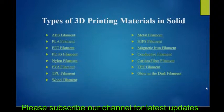Okay, talking about the materials, I hope ABS and PLA are known to everyone, and we also have PET. ABS stands for acrylonitrile butadiene styrene, PLA stands for polylactic acid, PET stands for polyethylene terephthalate, and PETG stands for polyethylene terephthalate glycol. Whereas PET and PETG are mostly used in the food industry and the medical industry, PLA is a biodegradable material which is commonly used for everything, and ABS is mostly helpful in industrial areas.